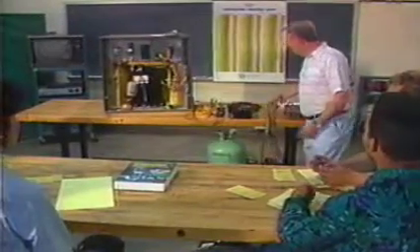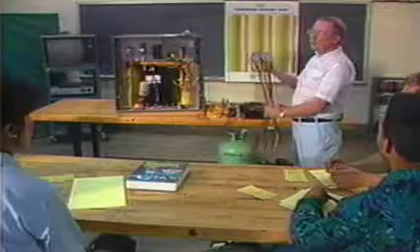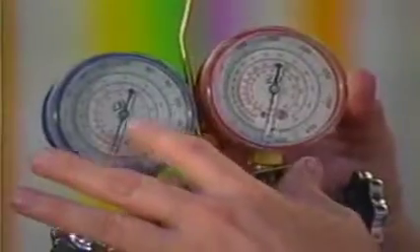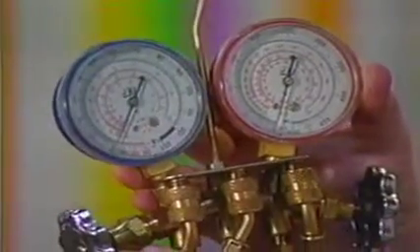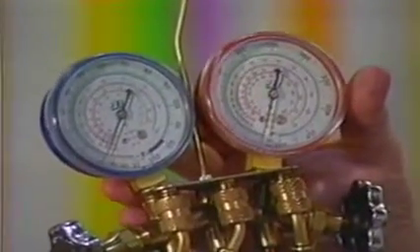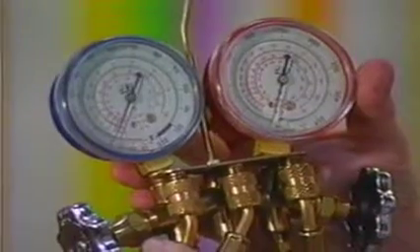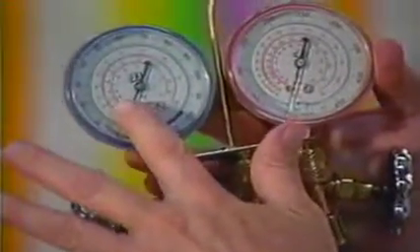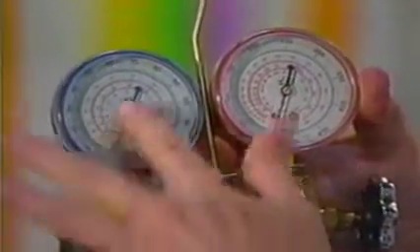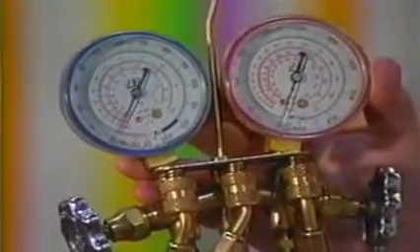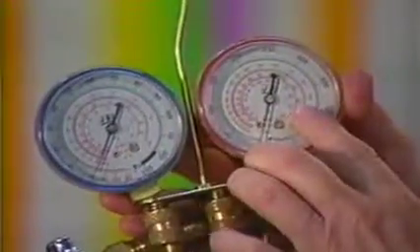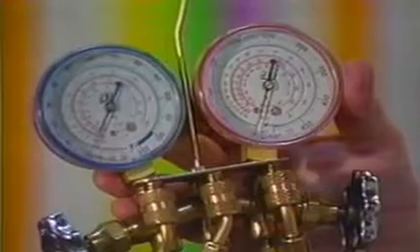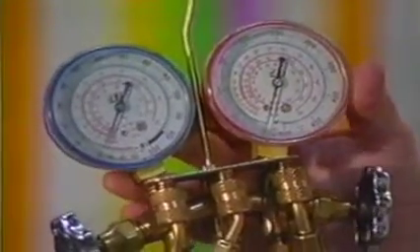Let's take just a few moments and talk about how the service technician would use the gauge manifold and what the technician would use it for. Printed on the front of this gauge, we have a lot of numbers, and they can be confusing. On the outside edge, in black, we have printed the pressures that we would indicate in the system. Printed on the inside, we have numbers that are temperatures corresponding to those various pressures. The temperatures correspond to three basic refrigerants commonly used in the field: R502, R22, and R12.